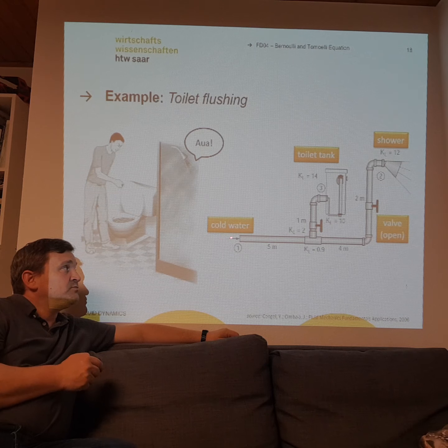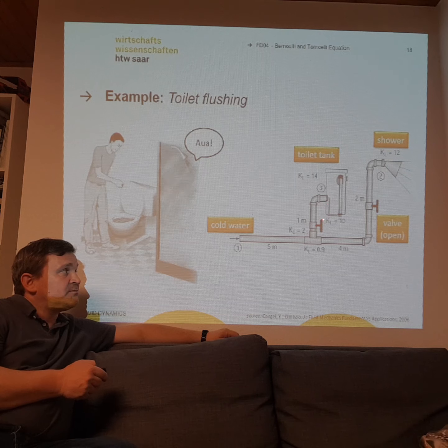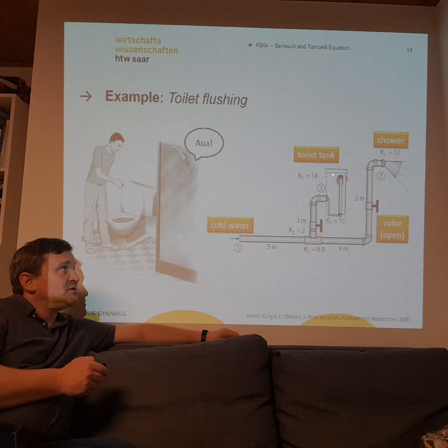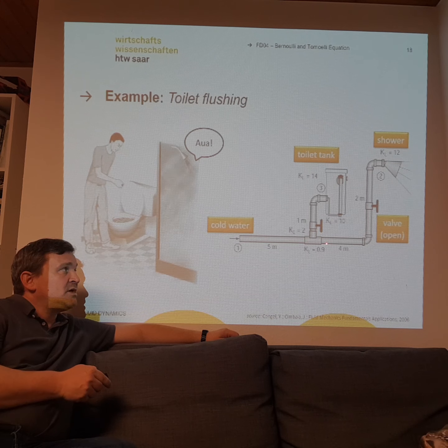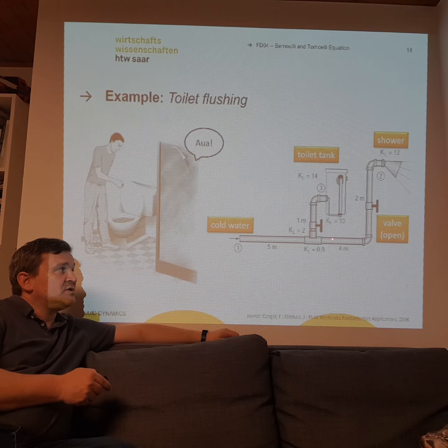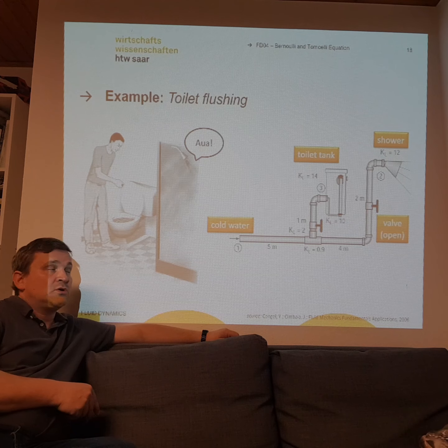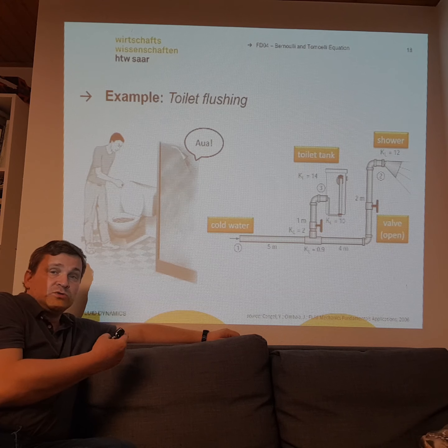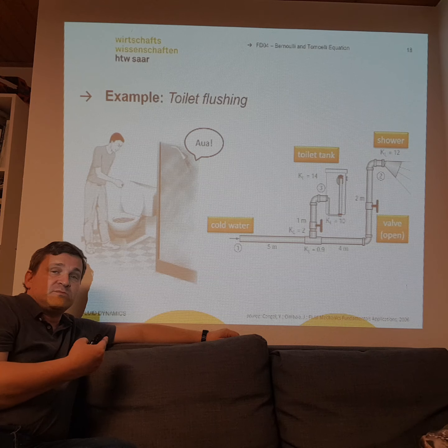But if someone now flushes the toilet, the cold water valve here to fill up the toilet tank, you get a pressure drop in the system, and then the cold water for the shower will have less velocity, less volume flow, less mass flow, and then you have more hot water, and then your feeling is as if the mixing temperature is much hotter.